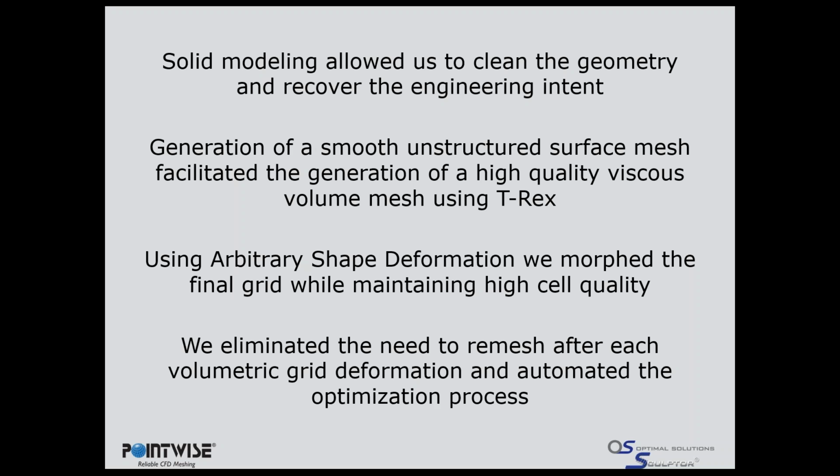And then we were able to generate the very smooth, unstructured surface mesh that facilitated the generation of a very high quality volume mesh with T-Rex. And then in Sculptor, using arbitrary shape deformation, Mark showed how we can morph that final grid while maintaining very high cell quality and eliminate the need to remesh after each deformation and automate that optimization process for possibly hundreds or thousands of designs, however many you have time for.